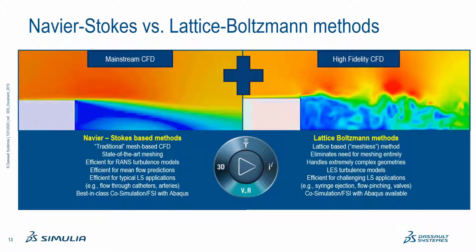Lattice-Boltzmann methods have not been available until relatively recently in simulation history, but they are gaining favor quickly for their ability to solve the toughest of fluids problems with highly deforming structures, high levels of turbulence, and pinched flow. A major advantage of LB methods is that they are meshless, which makes for some very important advantages.